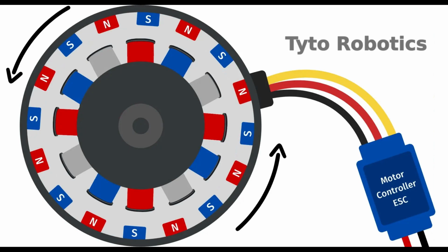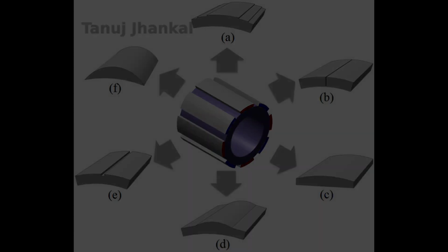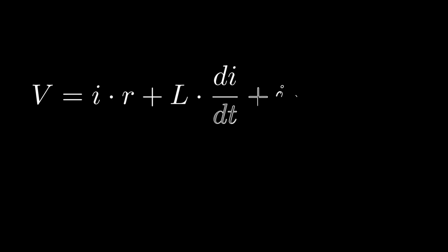We can see here that the permanent magnets are inserted with alternating polarities, and so the flux changes in the same manner. The shape of the flux depends on the motor construction and the shape of the permanent magnets. In this simulation, I assume a sinusoidal flux from the permanent magnets with the option of adding harmonics. So what we're left with is the following equation.